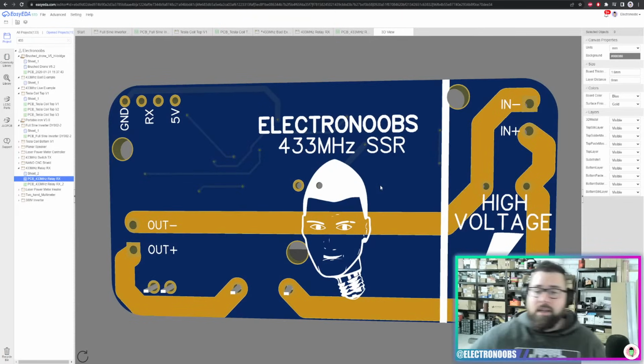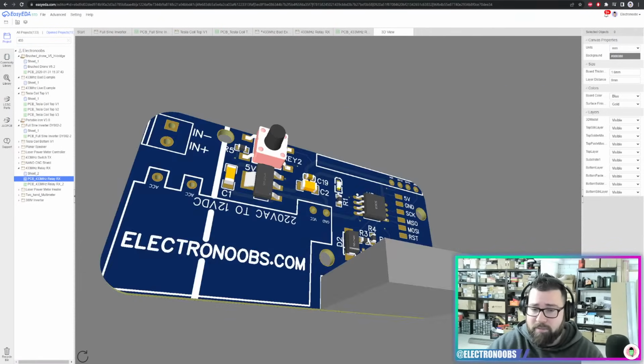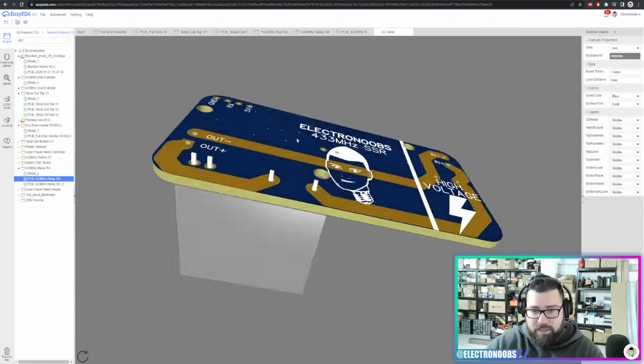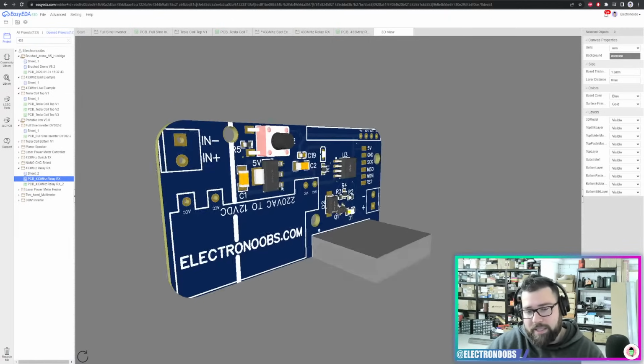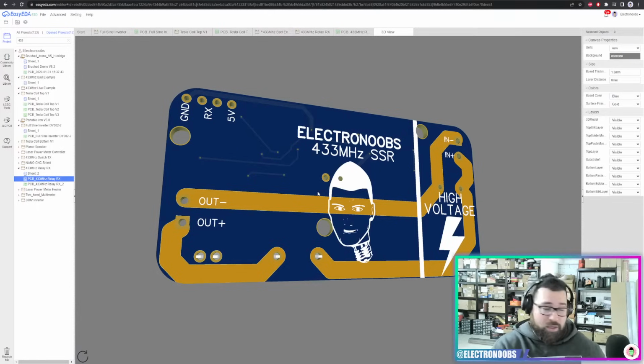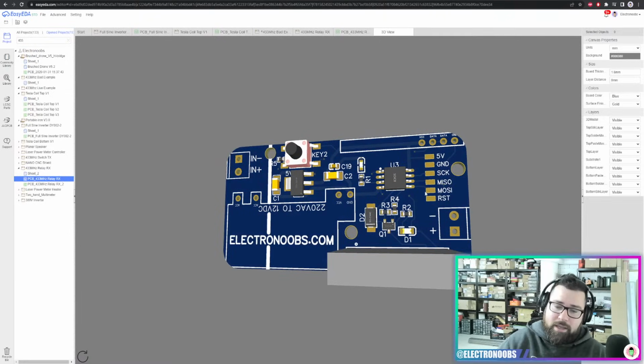Be very careful and make sure that you never touch the PCB while it's connected to high power. Actually, I had a lot of bad comments on this project because a lot of people told me that this was very dangerous. But you should never touch this PCB. Why would you touch such a PCB when it's connected to power? Usually what you will do to install this PCB is to go to your electric box, pull down all the fuses, cut the power for your entire home, install this, connect the wires, install it in your wall or in some sort of insulated box, connect it to your light, and then turn back the power, and never touch the PCB.